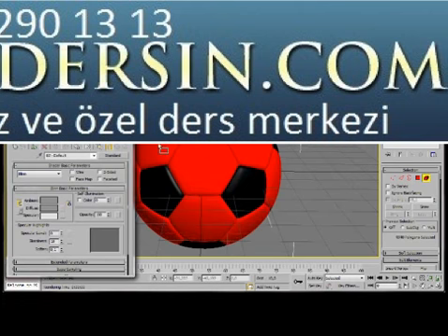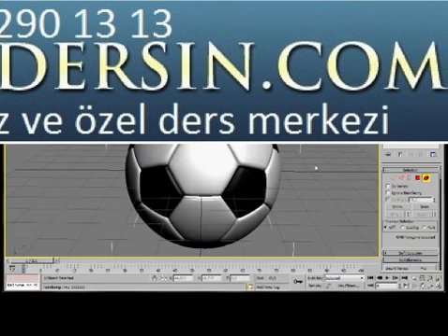We're going to drag it to the color elements, and we're going to change the diffuse color to white. We don't want a pure white, so we'll just drag it down to there. We're going to change the specular level to 50, glossiness to 25. Close the material editor, click anywhere in the screen. How's that?